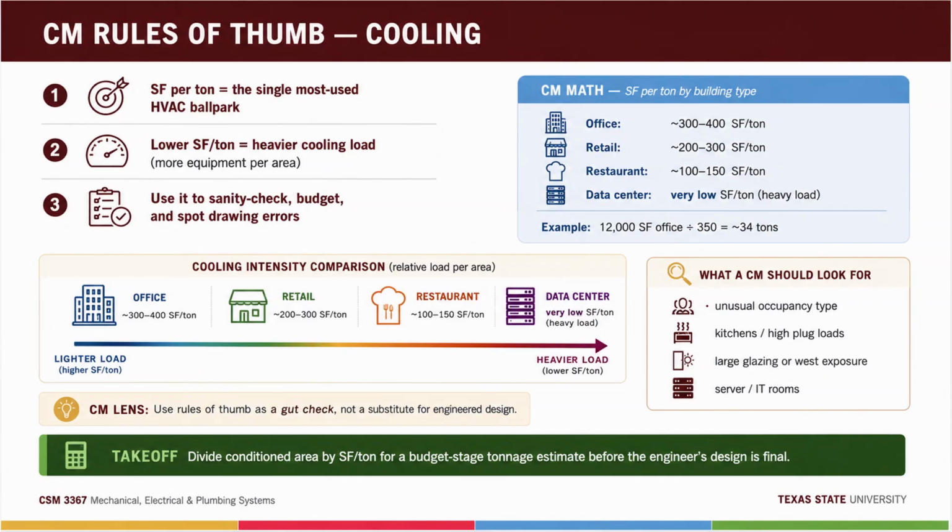So the calc is dead simple. Lighting watts times 3.412. Engineers usually carry it as a power density, watts per square foot. A modern LED office at around 1 watt per square foot, 10,000 square feet is 10,000 watts, times 3.412, about 34,000 BTUs per hour from lighting alone.